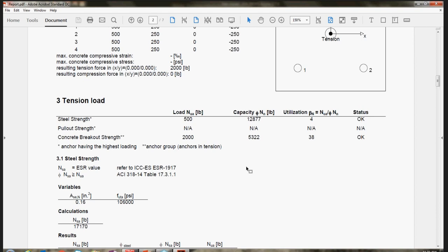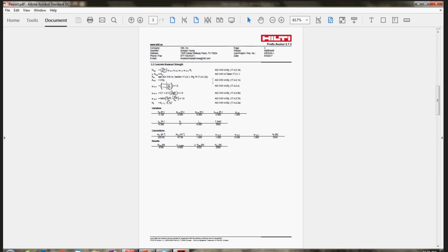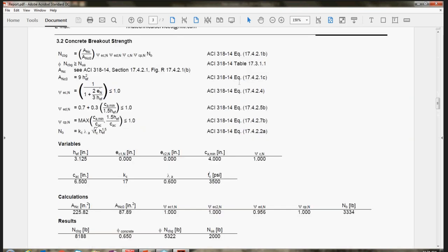And now I'm going to change the concrete member thickness. So you'll note that it's very simple to go ahead and make these changes on the model. You just simply double click on the geometry and you'll be able to make that change. Now for load inputs, we have 2 ways that we can do this. We can do this either on the physical load itself by clicking on the parameter and inputting our load. So we've got a 2,000 pound tension load.